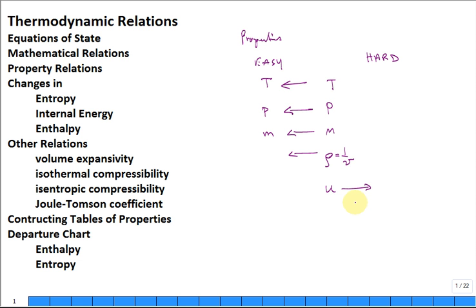But you know, we never really talk about internal energy as a value by itself. It's always with respect to a reference state. We often forget about that reference state, but it's embedded in the tables and you can often find it and remind yourself. So it's really the change in internal energy. Mass truly is measured from no mass up. There's not like negative mass. But you can have negative internal energy because maybe the condition of the state is colder than the reference. So we talk about changes in U.